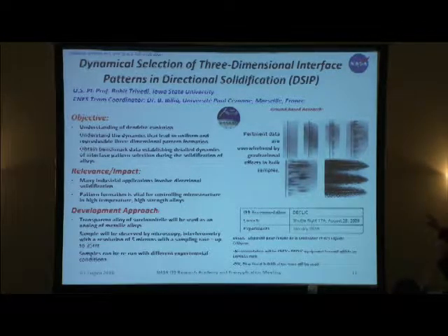Matter of fact, the fluids can break up some of those dendrites and really change the nature of the microstructure. Also, those dendrite arms really can be affected by the fluid motion. So the reduction of gravity and elimination of fluid motion have a very significant effect on the shape and form of those dendrites. And so we are essentially generating here a unique data set in microgravity, which we can use to test the validity of the various dendritic solidifications proposed.